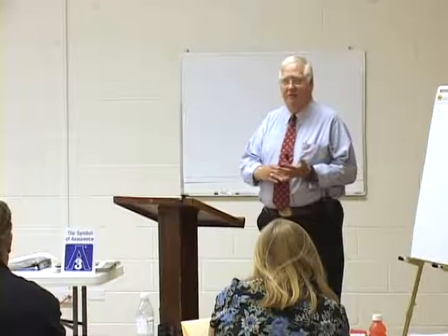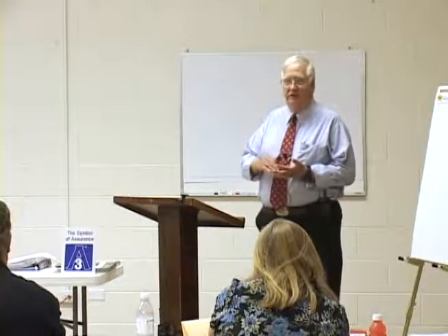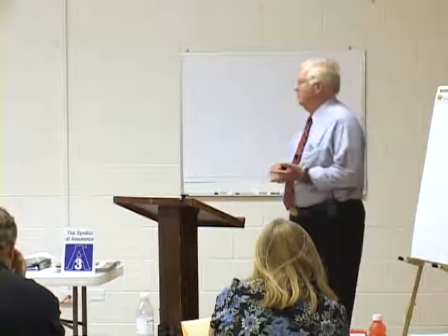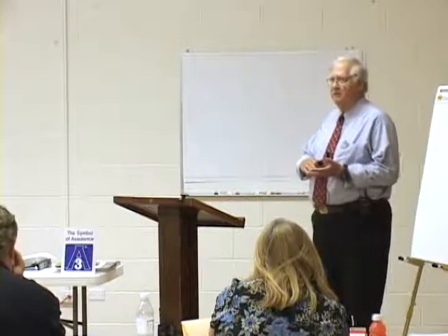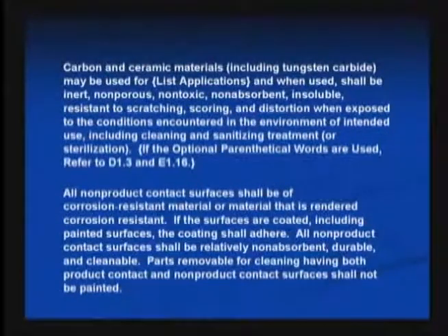How well does it stand up to butterfat? How well does it stand up to the cleaning solutions and acids and caustics that are commonly used in the food industry? So are these materials durable enough to be used? Other materials that can be used are carbon and ceramic materials, very commonly used on pump seals, rotary seals.